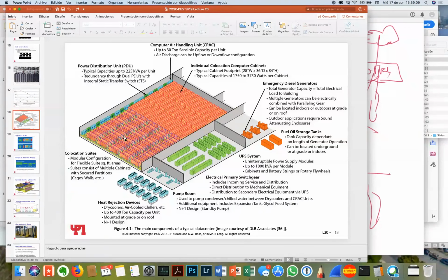And you have these big metal buses that connect all of them together, one into the other. Data centers often run on DC, depending on the type of environment it's in. They don't run on AC, so yes, you build servers that have DC power supplies. That's all the power supply in your computer does, is convert everything to DC anyway, so might as well get rid of those and just hand it DC to begin with. So that's the way the phone network's always been built, on negative 48 volts DC, for example. So these batteries are built to do DC anyway, so that's what they do.